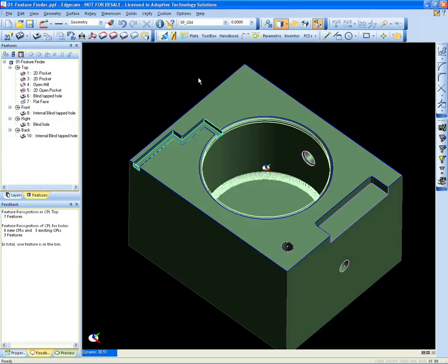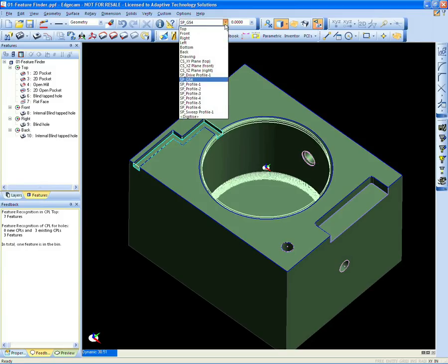One other thing I want to touch on here is this CAD link data that's usually misunderstood. As you can see, the work planes and sketch planes have been transferred from the CAD system, again the ones I've been mentioning, and as you can see here we just created a sketch plane called G54. So in that drop down list you can easily select that and define where your coordinates are going to be relative to or from. So this is another nice tool that can be used that people don't often take advantage of.